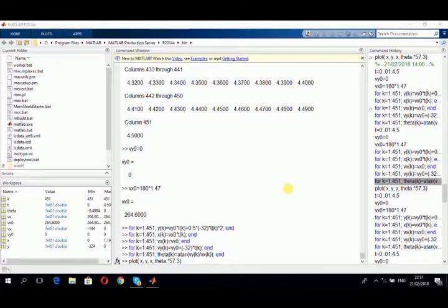At the beginning, we need to have a glance over the Matlab windows. Start with the current folder window. Here you can find all the files and folders inside the current folder. Here is the workspace window that includes all the current variables with the relevant dimension for each variable.